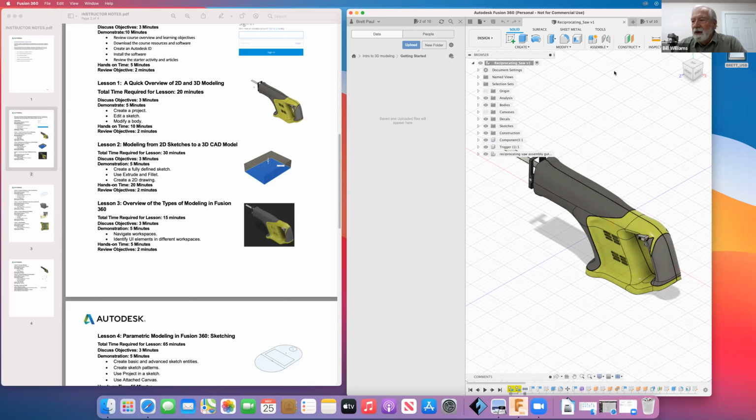Okay, good. Yeah, it's after you've created a sketch and you've decided you want to have another plane. So let's say you do another plane. You have to do the finished sketch first before you move to the next plane. I'm not quite sure about that. You do. Yeah, as a matter of fact, you have to finish sketch before you do anything. Okay, yeah. But you can go back into the sketch later.